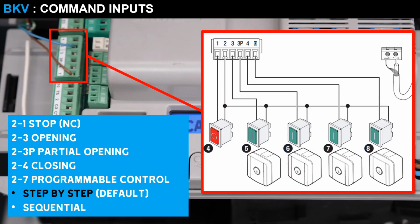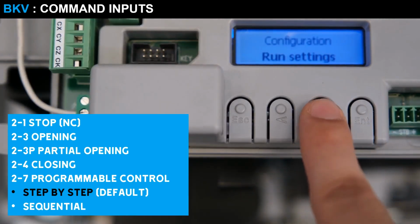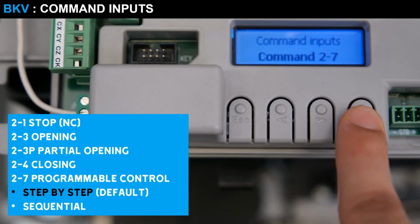To control the gate you can use one or more of the 5 command inputs: stop, opening, partial opening, closing, and programmable command. In case of using input 2 and 7, it will be necessary to configure the type of command between step-by-step and sequential.